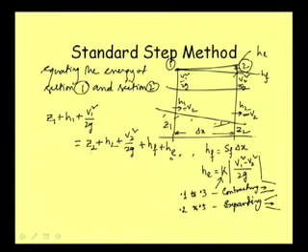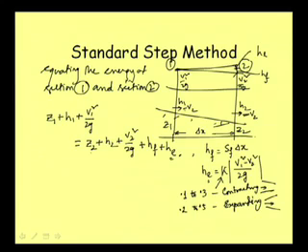Now, in the standard step method, we generally do not prefer to go for a non-prismatic channel all along, but wherever necessary we go, and in that case if some expanding portion is coming, then we can calculate this HE value there.